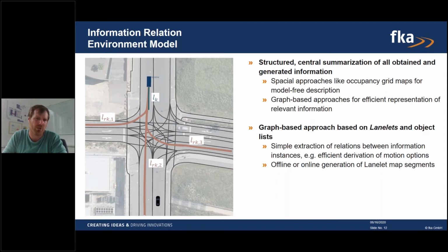You can, for example, think of occupancy grid maps. What occupancy grid maps do is they just look at a single location around you, or in your world coordinates, and say, I think there is this cell. You normally discretize it with cells. This cell is occupied with a specific distribution, or you are sure by 80% that in this cell you have an occupation.